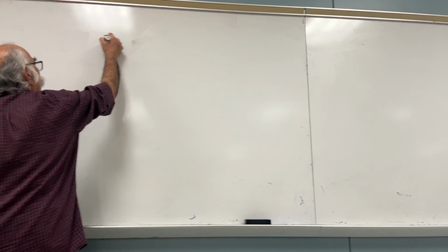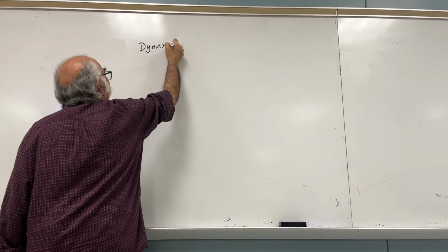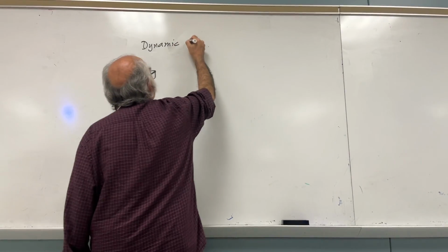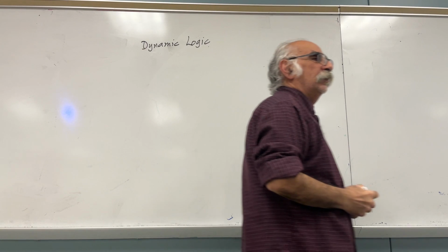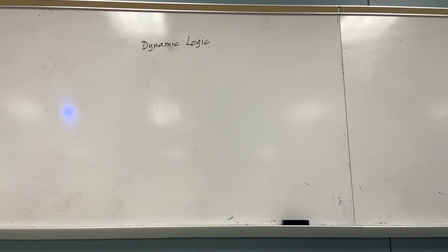Last time I introduced you to yet another type of digital logic technology, which is dynamic logic. Very quickly, let's review it. What is dynamic logic? In dynamic logic, the logical level is taken as the voltage stored across a capacitor, rather than having a path to VDD or a path to the ground. The beauty of dynamic logic is that you only need to implement the logic using the NMOS.